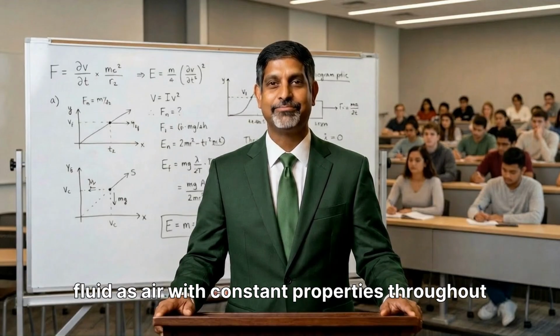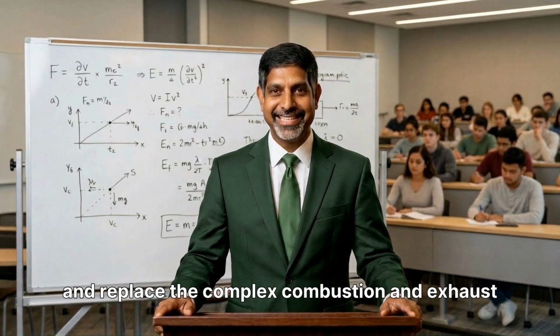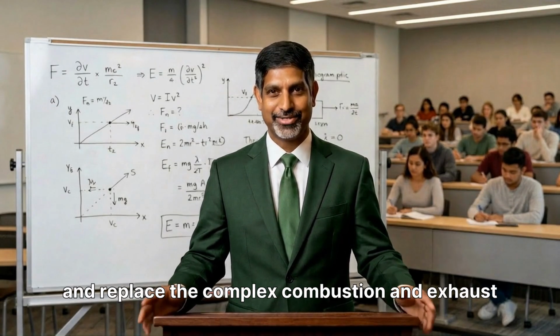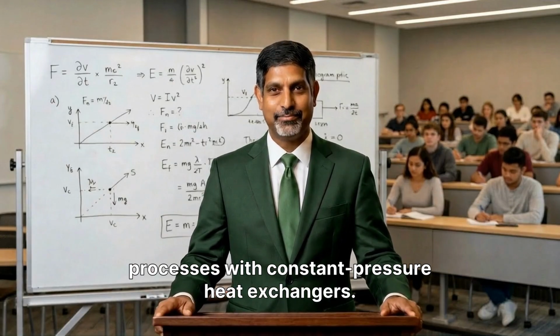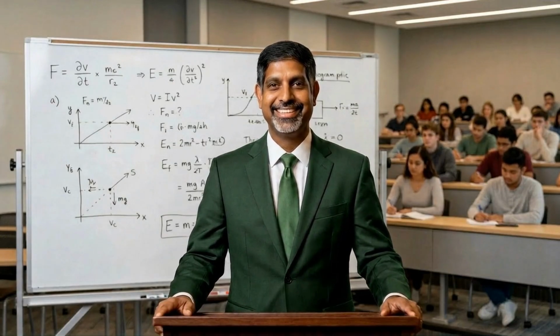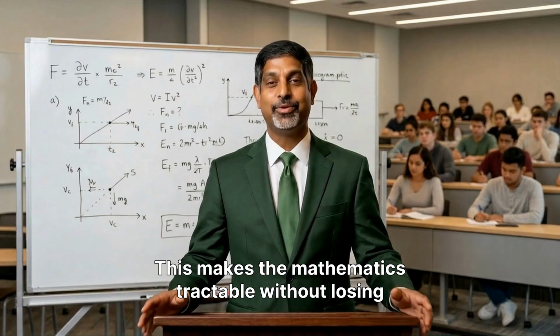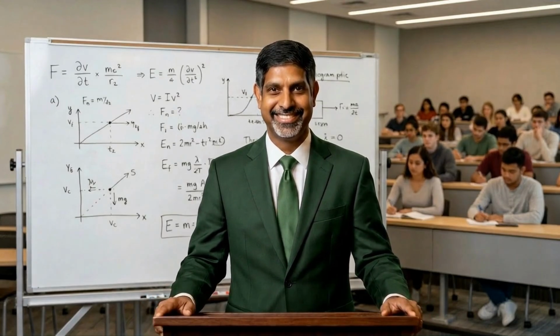We treat the working fluid as air with constant properties throughout and replace the complex combustion and exhaust processes with constant pressure heat exchangers. This makes the mathematics tractable without losing the core physics.